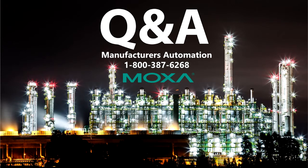They could be controlling a drilling rig, for example, a land-based drilling rig. It can be inserted into a dashboard of sorts, so it can be regarded as an embedded system. And in that case, the full unit being IP66 regulated might not even be a necessity. It could only be applicable to the actual front pane and screen. So that's one answer for that scenario. If it's self-standing and it's out in the desert, for example, and it's functioning almost as a mini control room, it's not just an HMI. It's actually a control center of sorts, and it's on an oil platform.